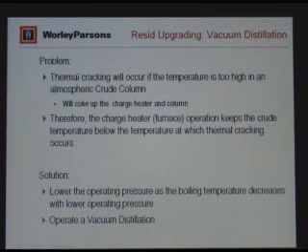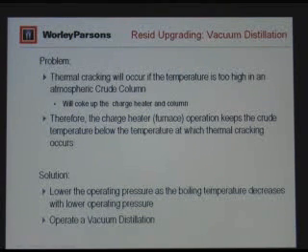All right, the first thing we're going to talk about is vacuum distillation. Now, a vacuum column, we have to think about why we go to a vacuum unit. Now, vacuum units are tricky and they're difficult to operate in a certain sense because as soon as you go below atmospheric pressure, you run the risk that air is going to leak in to your unit. And because we're dealing with hydrocarbons, if you allow air to leak in, you always run the risk that you're going to have a hydrocarbon-air mixture, and if you end up with sparks and things like that, you can have some kind of fire or explosion.